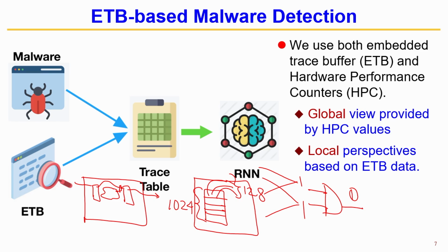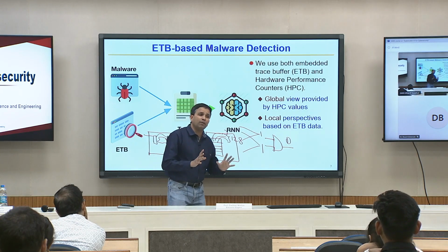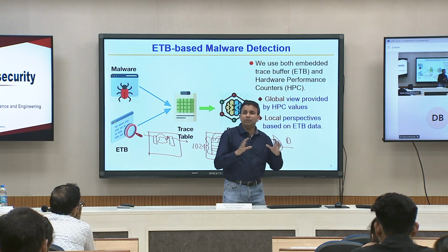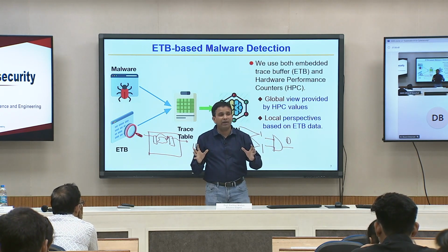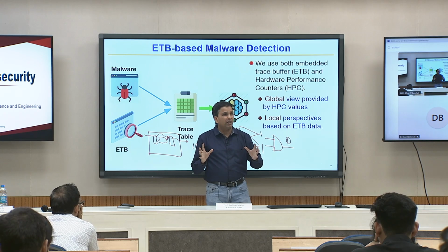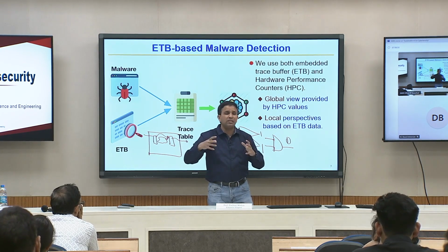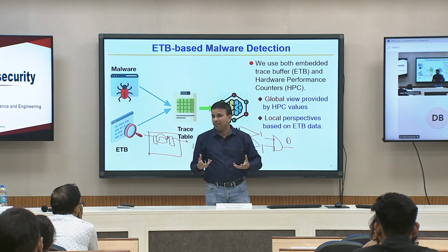The scan chain idea came from a different point of view; that structure gets inserted by a different set of people, manufacturing testing people. The reason they inserted it is that when they want to test a chip for manufacturing defects, they need to pump values into these flip flops to initialize them to a known state.